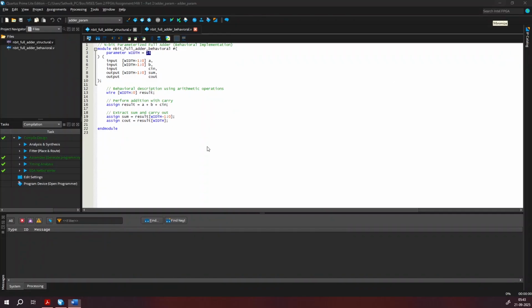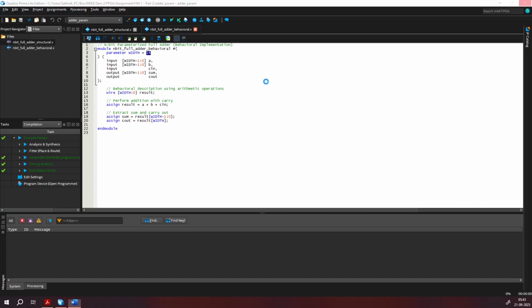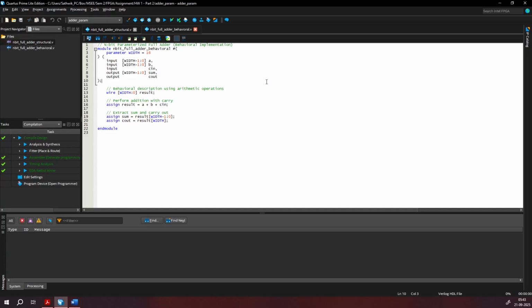So yeah, that is the experiment that we performed on a full adder, starting from 1 bit in its most user-friendly way of designing, that is a schematic design, extracting an RTL out of it, running a test for the RTL, then writing our own RTL based on the combinational logic, testing that using a test bench, simulating and validating the result.